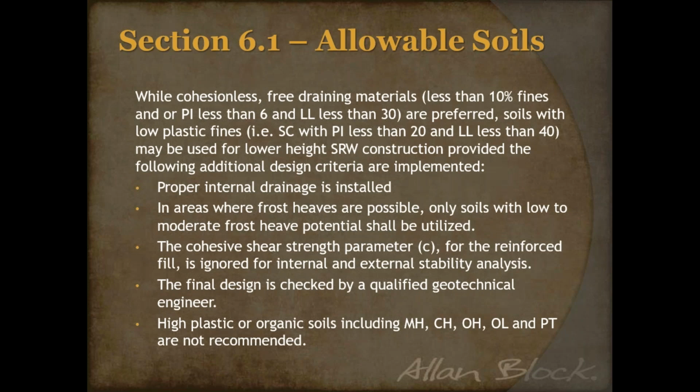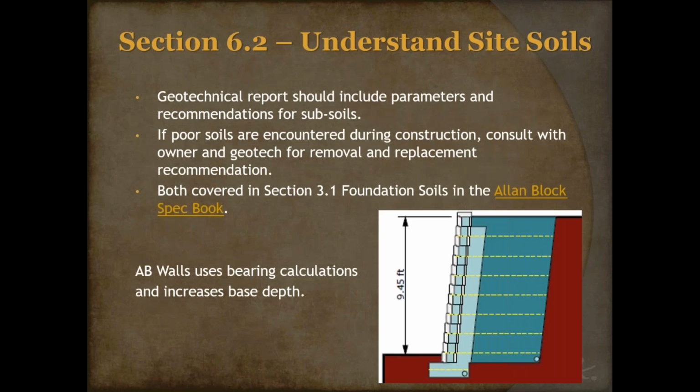And then the last point when it comes to the allowable soils is obviously when you're talking about that heavy clays, that high plastic material, that can't be used. And so plain and simple, we just remove that, then you are going to be using some type of a select backfill.